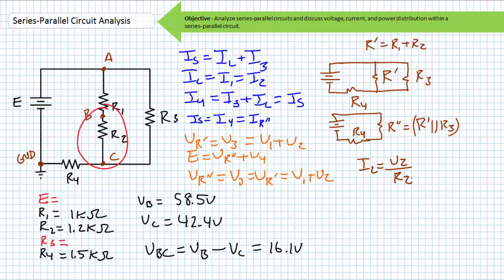Ohm's law says that I2 equals V2 divided by R2. Substituting in the necessary values, we find I2 equals roughly 13.4 milliamperes. This is an approximation, and my recommendation, consistent to the advice I issued way back in the DC math lecture, is to make use of the full unrounded values via the previous results key in your calculator. If you don't follow this advice, your answers will progressively depart from mine as rounding errors accumulate. I2 is known to be 13.4 milliamperes.